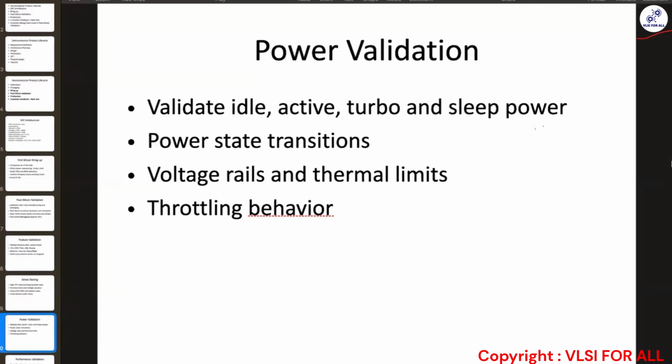Along with that, when you connect some devices, devices have their own states as well. When you connect a USB, you will have different states for that also, like USB U0 or USB suspend. Or if you're connecting any PCI related devices, you will have L0, L1 or L1.2. All of those states will be there, so that can also be a cause to block your residency. You may have to check if such an issue comes up.